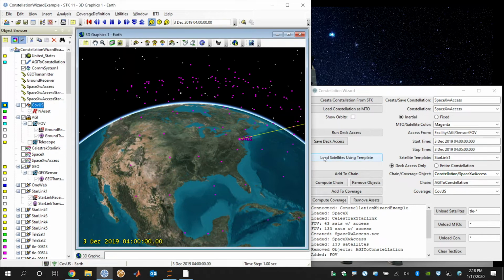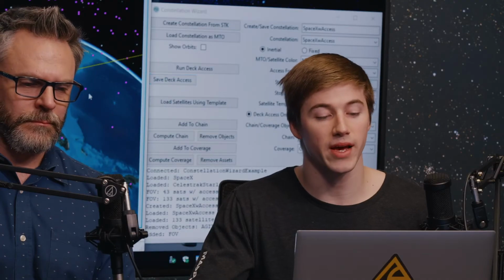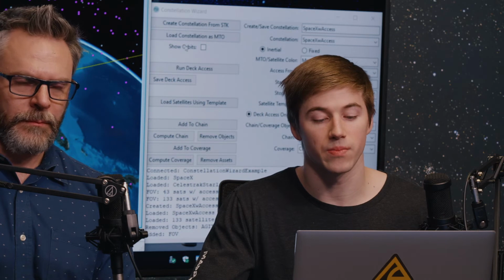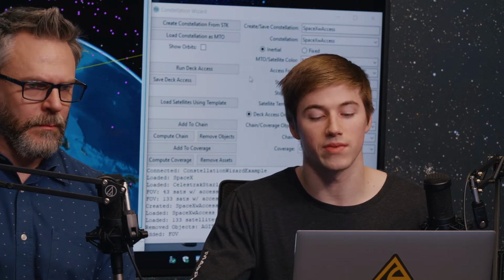I'm just going to uncheck that guy. And you could do finer resolution on that if you wanted to, right? Because we're just keeping it quick. So in the interest of time for the video, you can increase the resolution of that coverage grid quite a bit and use parallel computing to distribute the load to other computers if you had a really big problem. Yep. Okay, so that is the main abilities of the Constellation Wizard.